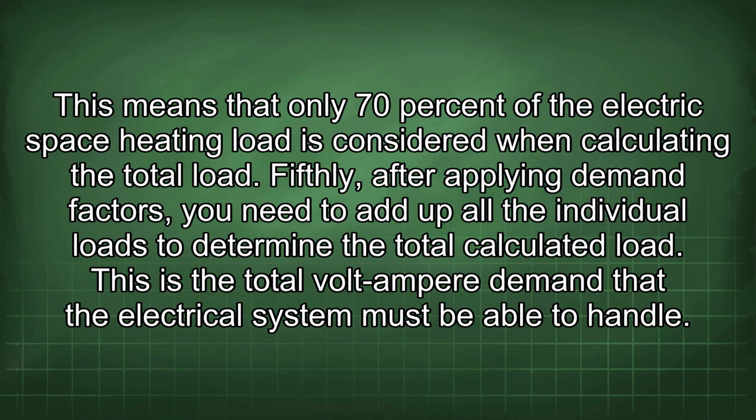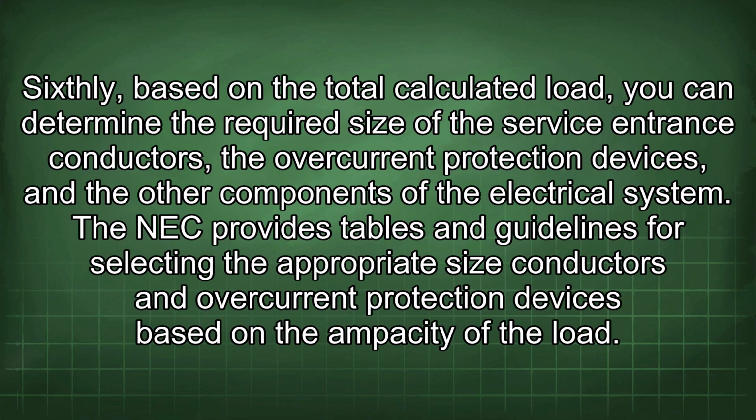Fifthly, after applying demand factors, you need to add up all the individual loads to determine the total calculated load. This is the total volt-ampere demand that the electrical system must be able to handle. Sixthly, based on the total calculated load, you can determine the required size of the service entrance conductors, the overcurrent protection devices, and the other components of the electrical system.